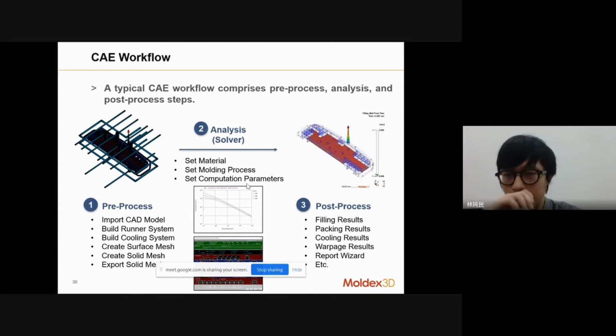And what's more, right now we have the different materials that I mentioned earlier, and also we have the machine response. For example, even on the same machine, maybe it's a different generation or something, so they will have a different machine response. It means even if you set the same parameter, the result may be different, because maybe they have some tolerance in their screw.